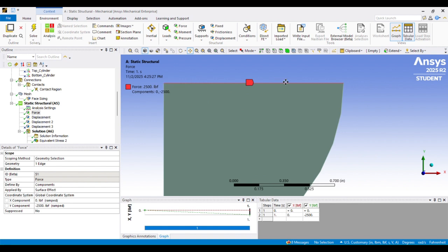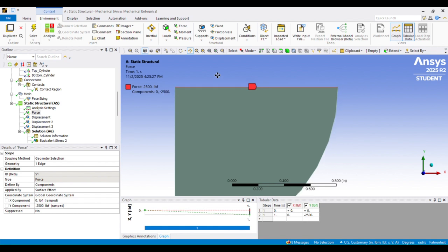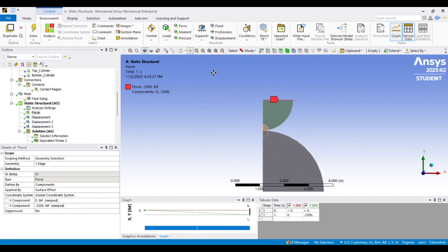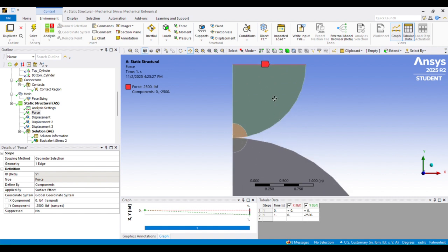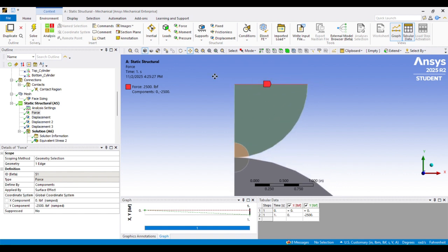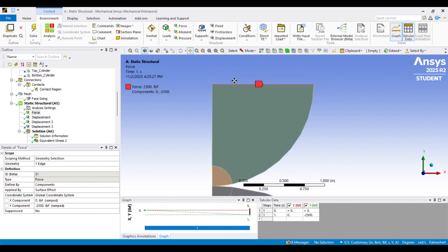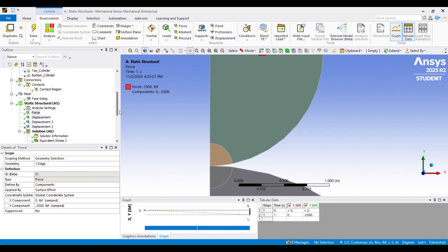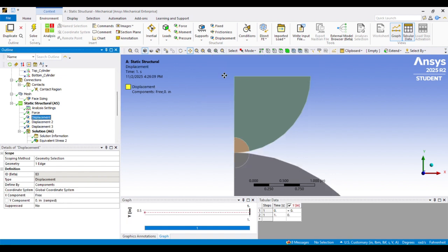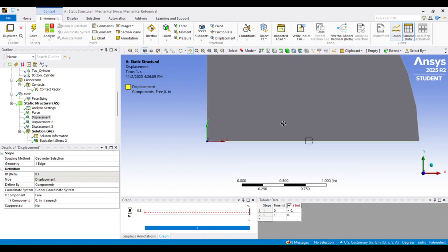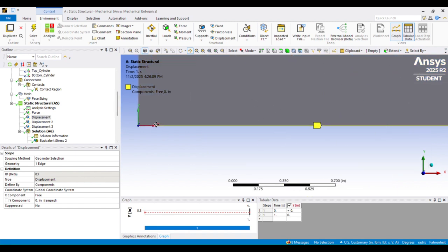And on the top, I've applied half the force of our hand calc because we're only modeling, even though it's a quarter circle, the applied force is only occurring on half the diameter. So you have to halve the force. And then now I've set up the boundary conditions. I've set this edge, I've set the displacement equal to 0.